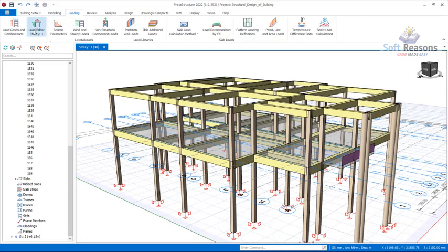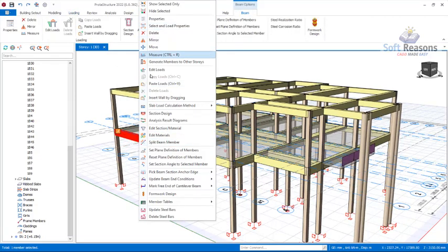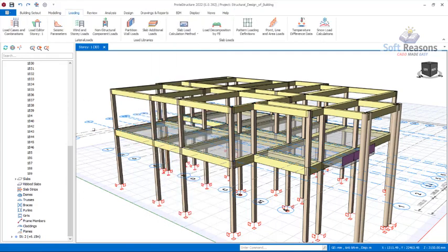So you can actually click on the load editor now, or you can right click. If you select any of the beams, you can right click, and then you see the edit load options in the drop down menu right there. Okay, but by then you have to navigate to the first floor. There are 2 ways to actually apply load to this structure.